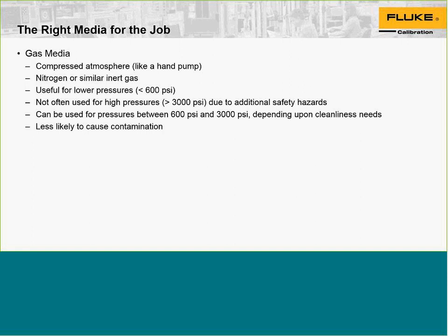With compressed gas, there is a lot of energy stored in that gas. If not treated properly, that energy can be dissipated very quickly, causing an unsafe event. So we'll use liquids or liquid media for high pressures due to this concern. It is possible to use gas as a media up to pressures as high as 15,000 psi when required, especially for situations where cleanliness is a concern.